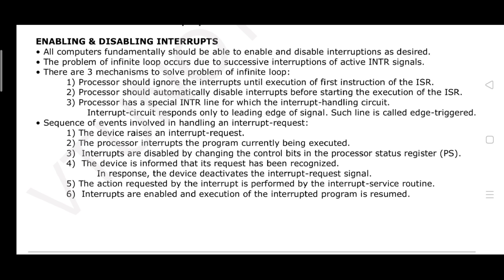Up to a certain level we can expect parallelism or concurrent jobs, but some of the jobs cannot be handled simultaneously. In that case, what happens? It will move into the infinite loop. So to avoid that, once it receives a signal from any of the devices, it simply switches to the interrupt service routine.